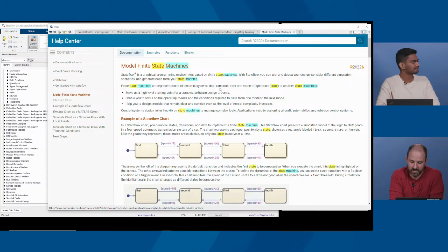It's a super handy tool, because if you imagine trying to debug state machines in code, it can be tricky. You usually end up with a lot of switch statements or if statements and conditionals, and you have to place breakpoints all over. It could be hard to figure out, and here you just see what's happening in real time as it's running.